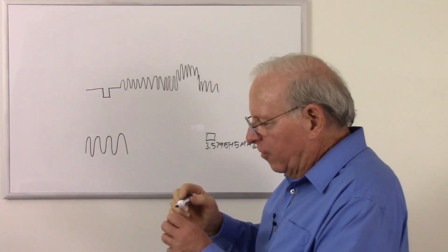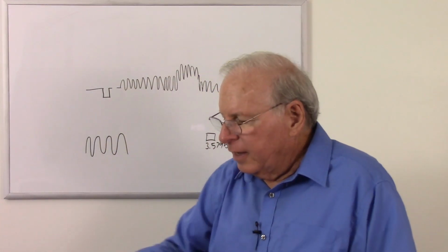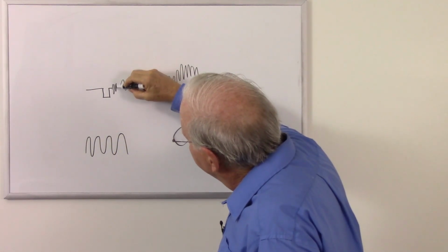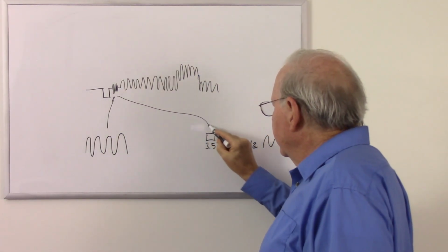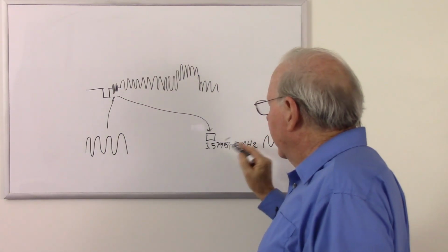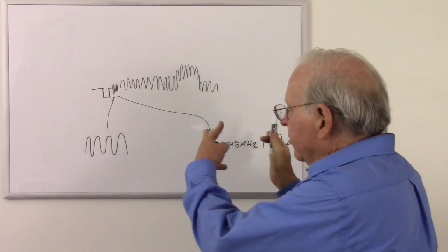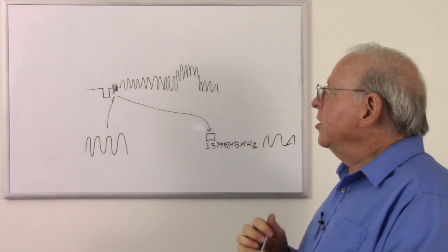How do we get those to synchronize? Well, I left a little something out right here. They send 8 to 10 cycles of the master oscillator there, and that is extracted from the signal and synchronizes the slave oscillator over here to make those two oscillators be in sync. So that's how they added color to the signal.